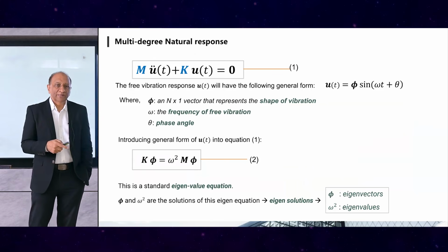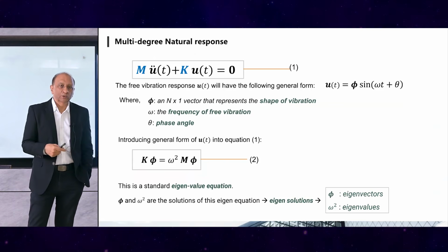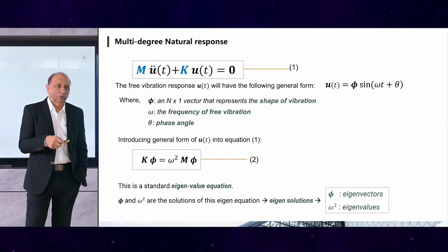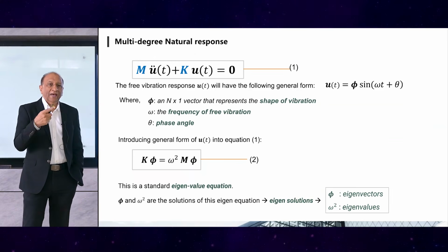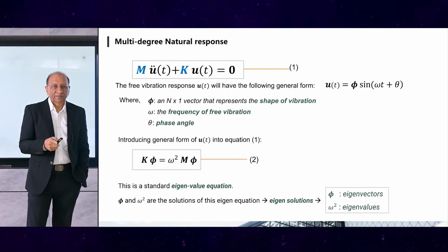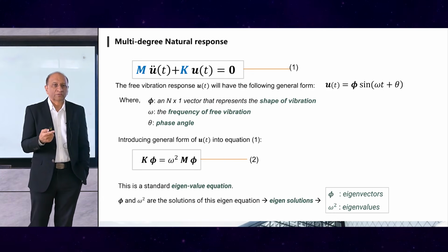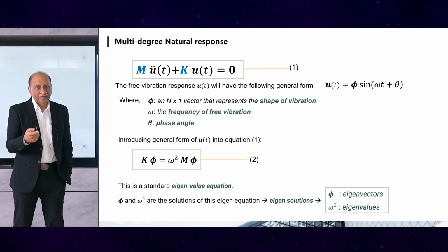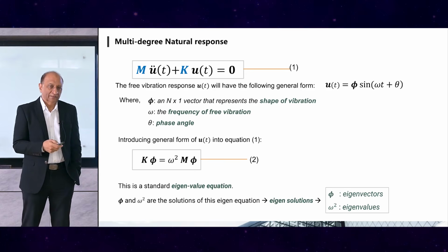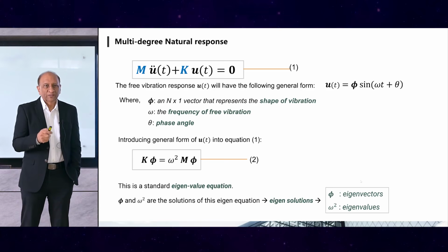So we can extend that to a multi-degree of freedom system, and we can solve the equation mathematically as an eigenvalue problem, and then finding the eigenvectors and eigenvalues, and they give us the natural frequencies and the mode shapes, corresponding displacement patterns for each of the modes. So this is how the programs use it. They use multiple ways to determine these, but eigenvalue analysis is one of them, which is the basic one, the primary one. There are, of course, other methods too. So this gives us the tools now in the programs to do that.